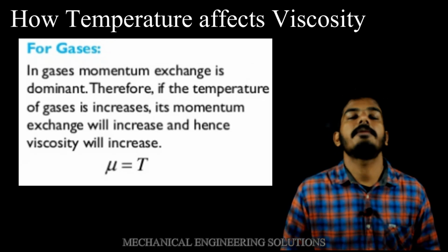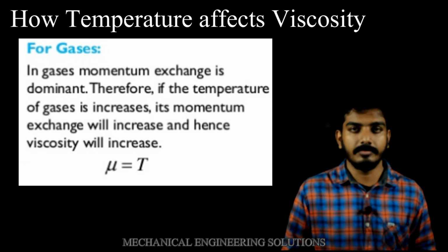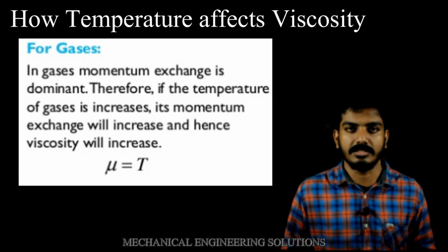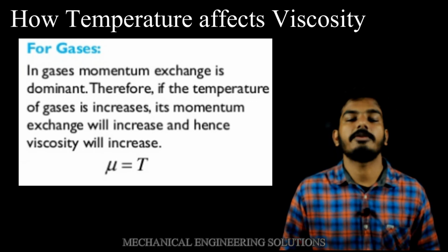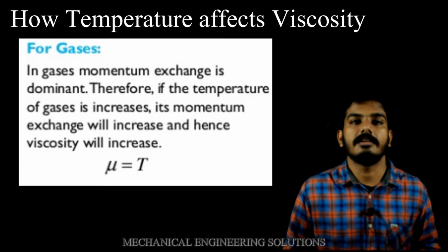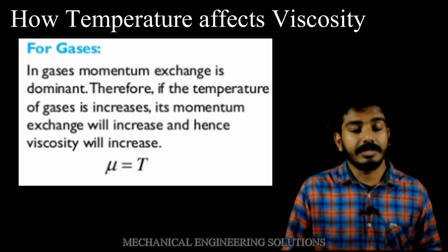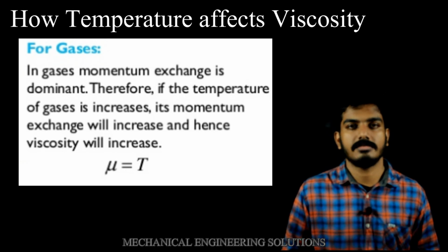In gases, the intermolecular spacing is already high, so cohesive forces are negligible. But in gases, the viscosity is due to the intermolecular momentum exchange between adjacent layers. When the temperature rises, the intermolecular activity also increases. This results in an increase in viscosity. So we can conclude that in gases, as the temperature increases, viscosity also increases.